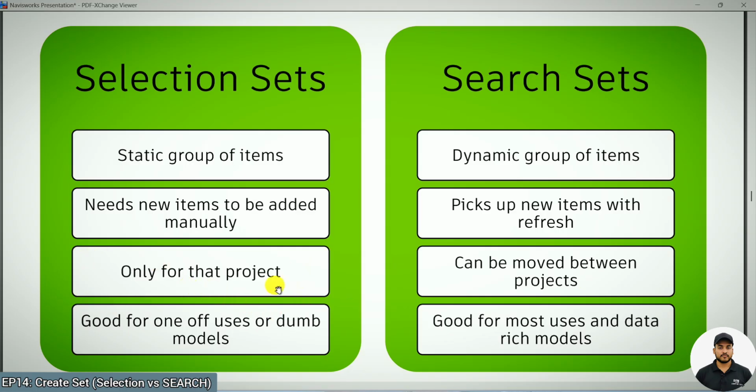Also, a selection set will be only for that project because in this we have manually selected, but a search set we can share with our teammates also because it is searched with some kind of properties. Okay, so let's start with the search set and the selection set.